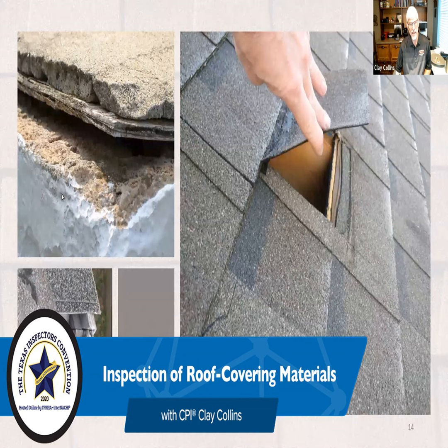So the underlayment has more than one purpose. If it's installed wet, you've got a problem. You install the shingles wet, you've got a problem. If you don't install them quickly enough, then you have all the dirt and the debris that comes from a construction site or from re-roofing, and all of that gets in there, and now you've added an abrasive material that can cause its own problem.